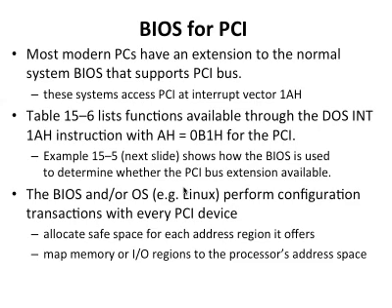Okay, we saw in the example that the particular Ethernet controller has been assigned addresses: for bar 0, that's a memory address, and for bar 2, that's an I/O address. But who assigns these addresses? It's the BIOS that does the job. Modern BIOS in the computer system has, as one of its functions, to scan the buses. It will interrogate the devices on the bus to understand what they are and also to decide which address to assign to the individual resources available in the devices.